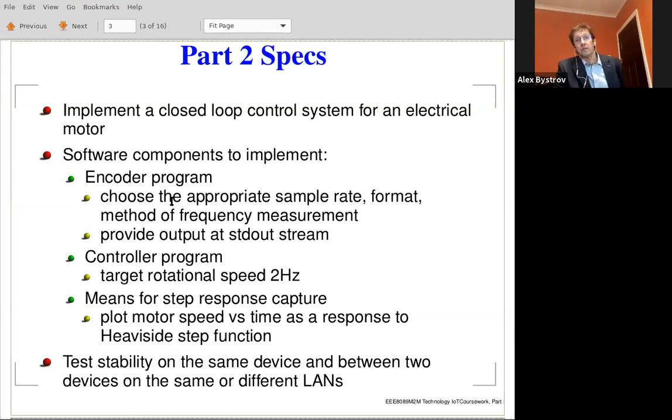And the other is to measure period. So you have this period which is one interrupt and the other interrupt. So between the interrupts you have this time interval, the period. And within this period you can fit multiple number of counts of a timer.